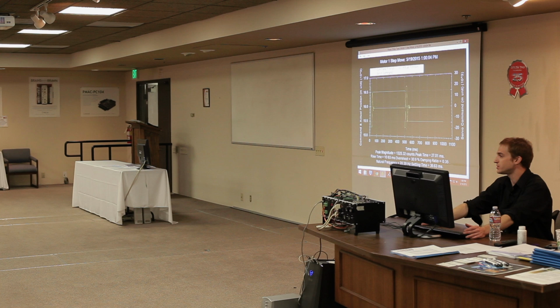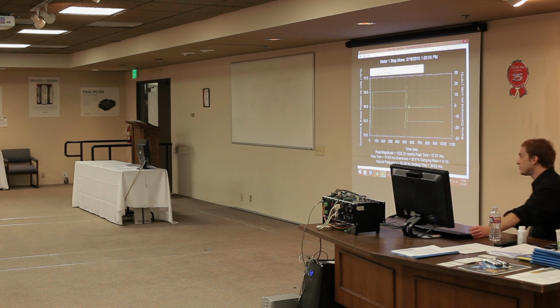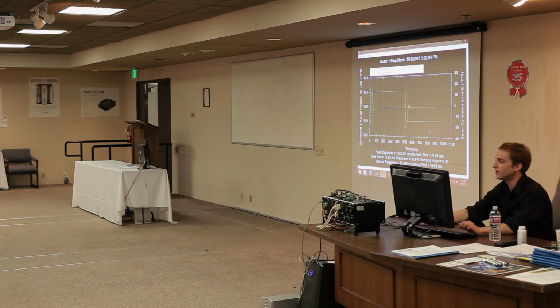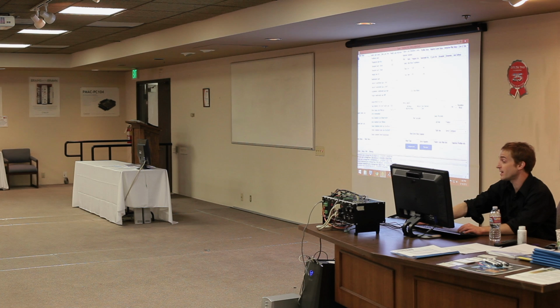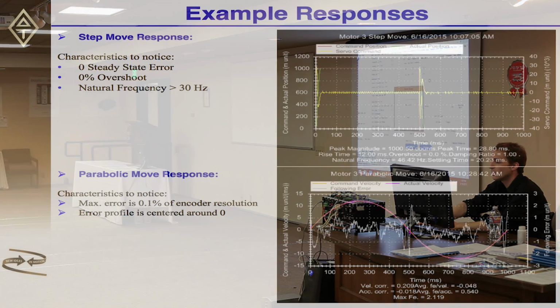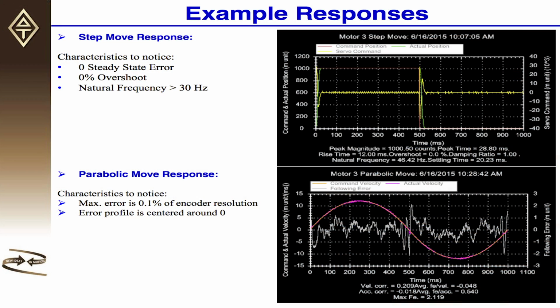And my natural frequency, you can see at the bottom there, is above 20 hertz. So I've achieved the criterion that I gave you guys for the natural frequency. Now we just need to damp out the overshoot and get rid of that steady state error. So to damp out the overshoot, I will increase KVFB by 1000. Now you can see that that overshoot peak is completely gone.